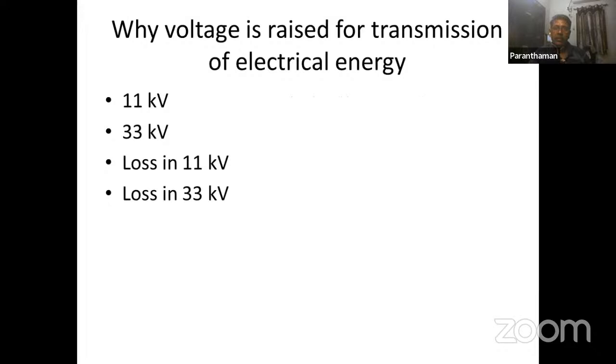The voltage raised for transmission of electrical energy from 11 to 33 kV, the loss will become 1 by 3 square, that is 1/9. This one we already discussed. We need not go into this again.